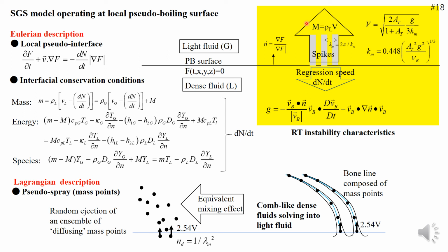The spike behaves as a free jet into the light fluid region and may play an important role in the transcritical mixing process. When such RT instability occurs, the subsequent flow evolution changes from the case where the instability is not captured. Therefore, a desirable LES should be one which could capture this possibility and predict two-way interactive evolution of flow.